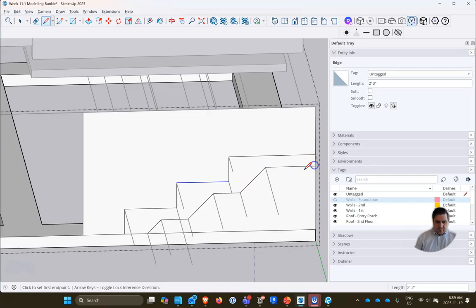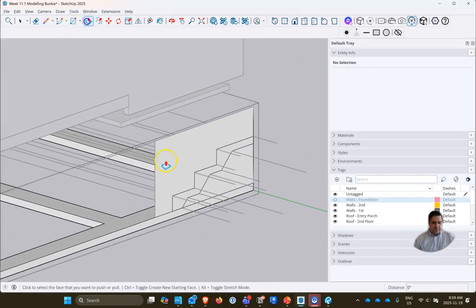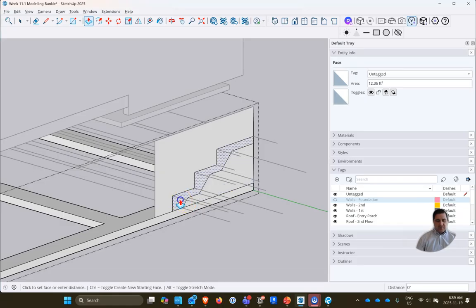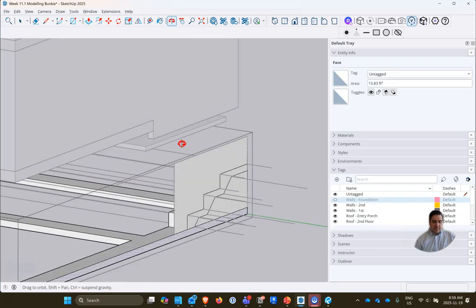And all the way across to there. And that gives us our extrusion. So it wasn't too bad. If it extrudes a hole like that, we can extrude and then hit the control button, and it'll keep that face on that other side. So we've got our footing here.